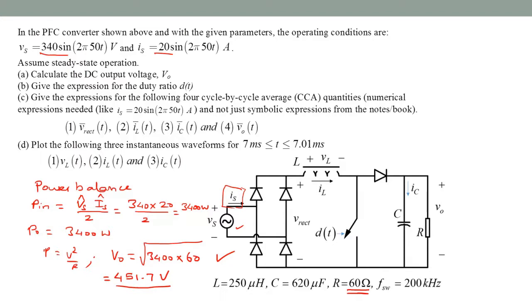And as a check, you can verify that this being a boost based PFC, the output voltage has to be at least greater than the peak of the input voltage, which is 340, and we are well above that at 451.